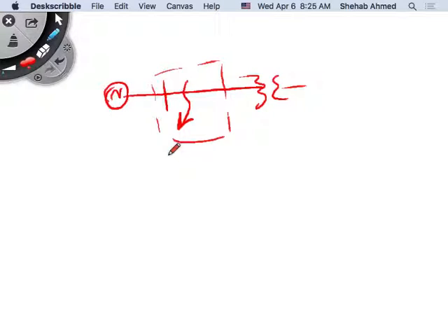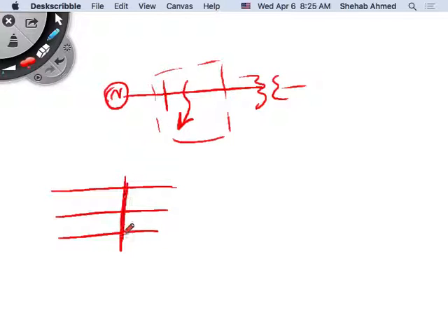This fault can be what? I have three phases inside. This is a single line diagram representation of a three-phase system, right? This fault can be all three phases touching each other, right? For example, some company was digging around the substation, and while they were digging, they accidentally cut the insulation on the cables and joined all the cables together. This is one type of fault.